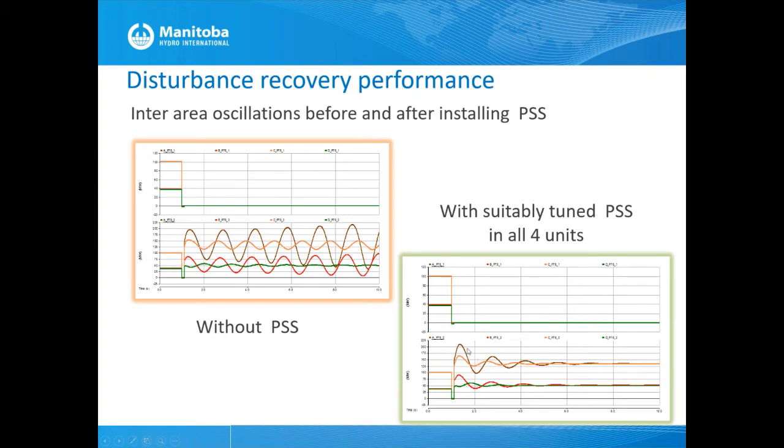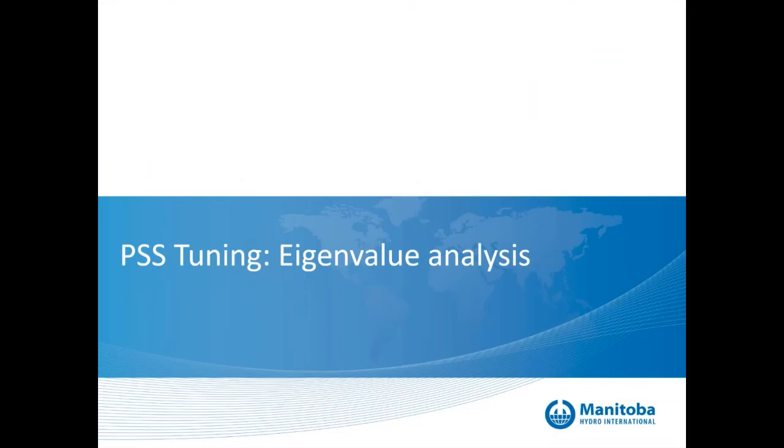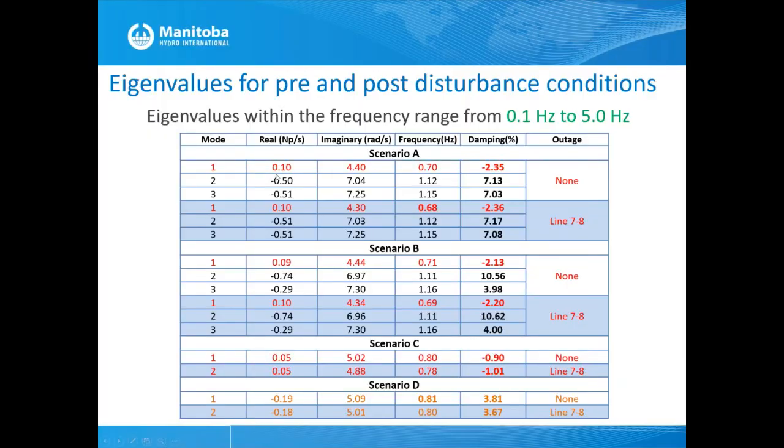Now if you go here, the first peak divided by the second peak is more than 1. So the log of that would be a positive number. That's how, when the magnitude goes down, damping becomes positive, and when the peak is going up, damping becomes negative. Also I have to mention, it has a really good connection to the real part of the eigenvalue. The eigenvalue for an oscillatory mode is a complex number.